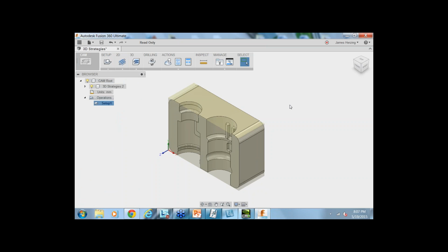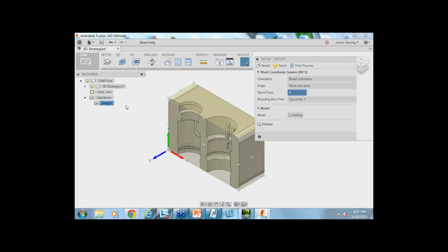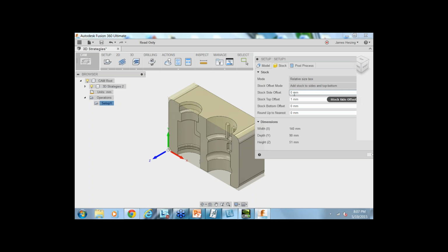So that was easy. So I mean, what's the top offset? Which one of those is the top? Well, you've got Z pointing up. If we edit this and go back here, let's put a 10 in here. And you can see it grow. So that did it around all sides. The top is the Z, pointing out. And we could just keep typing numbers in there as we so desire to find the rest.